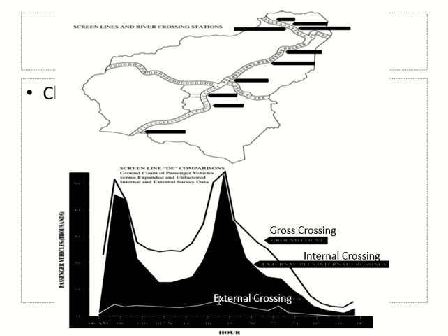Okay, and then we have few external crossings as well, which are very low compared to internal, and these external crossings are those people who are coming from some other area outside this region. Okay, so maybe they are coming from somewhere here or somewhere here, but they are outside the 2 zones between which I have put the screen line. So this you can see is very low, and this is how it should be. The internal should be very high. If it can be equal to total, it is excellent, but it should be very high, and the external should be very low. Okay, because you are interested in these 2 areas, so most of the crossing should be between these 2 areas.